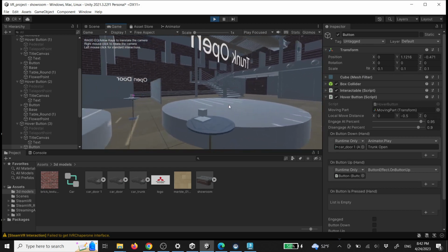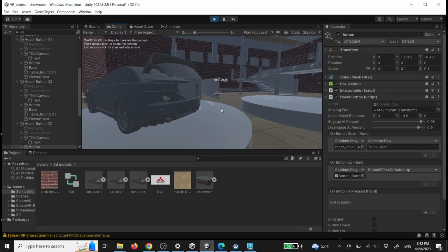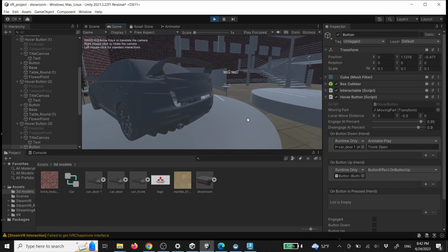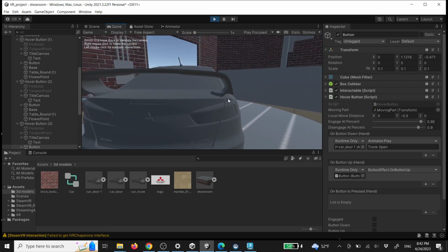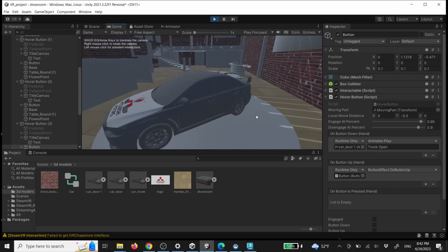And let's see for the trunk, since this was the problem, we're gonna have the trunk open and the trunk close. Okay, so keep in mind, if you have those slightly offset problems, and you adjust the pivot point, you should re-export your animation in order to compensate for that pivot point change.